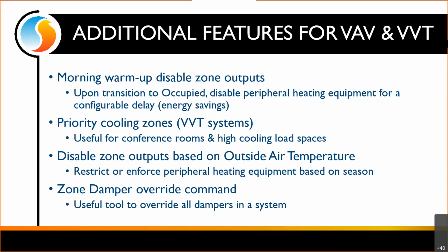Instead of waiting for the space to get cold, because we know it will get cold since there's a lot of windows, and then that cold reaches the thermostat, which will then command the valve to open, we could set a rule, something like, if ever it gets to -5 outside, I want those three-way valves open at least 10% or 20%.